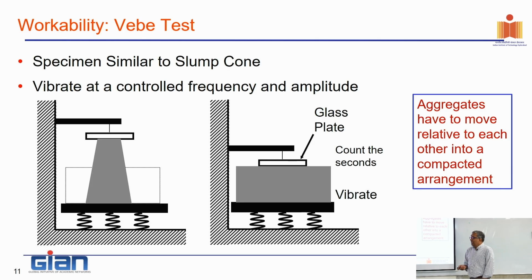Then what do we do? We measure the energy that it takes to make it fill the form, this container. So we would actually be vibrating the concrete. When you're vibrating, what are you doing? You're inducing energy. You're putting energy into the concrete, which agitates the concrete and gets it to flow. And in doing so, it will fill the container.